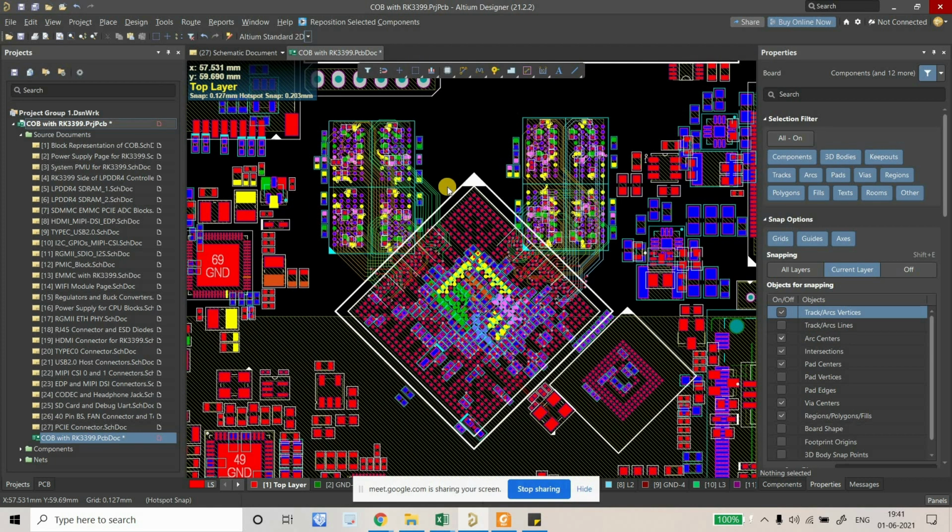So during the review process, we verify a lot of things. The review process basically starts from the requirement sheet, whatever the requirement sheet is, then we verify the schematic design, so that all the nets are connected properly. We'll go through each and every net.